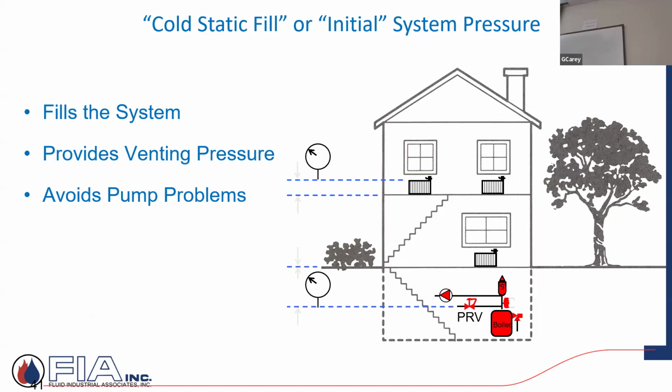The other thing we want to make sure of is that if we have any kind of venting requirements at that high point, which is not unusual, because all things being equal, if I do have some little air floating around, where's it going to find its way? It's going to go to the high point, right? Eventually, it's going to float to the highest point. So typically, I'll have some type of venting capability, whether manual or automatic, at the high point.